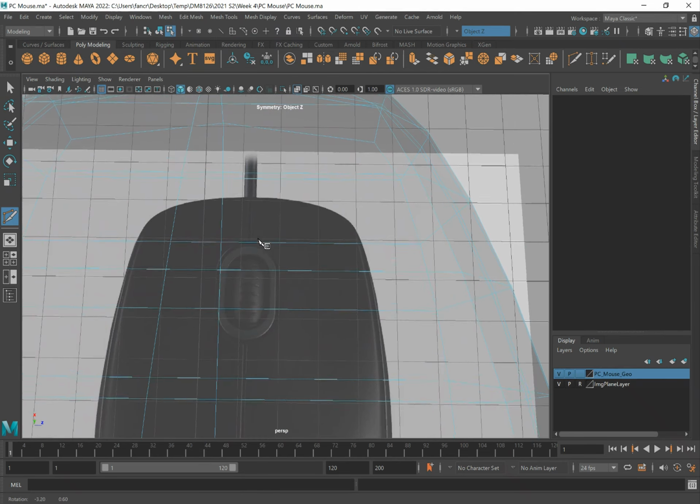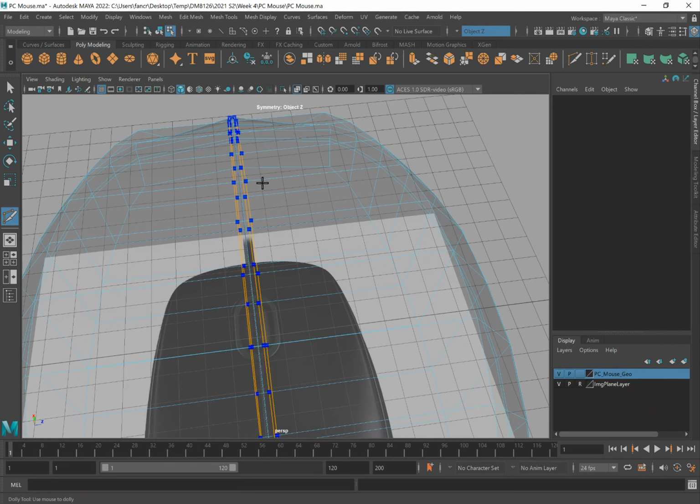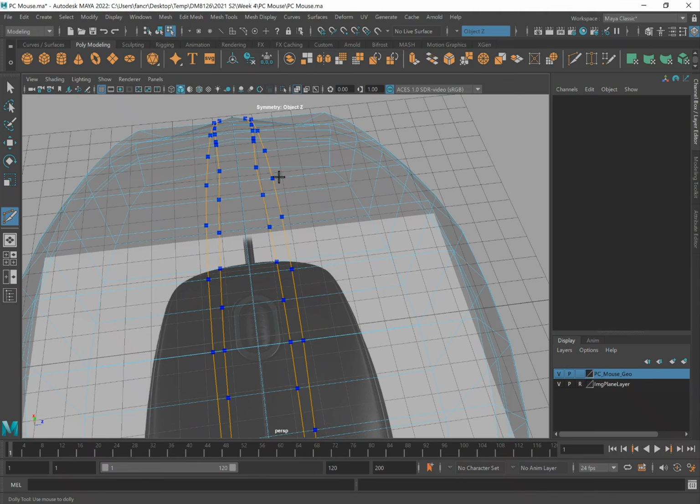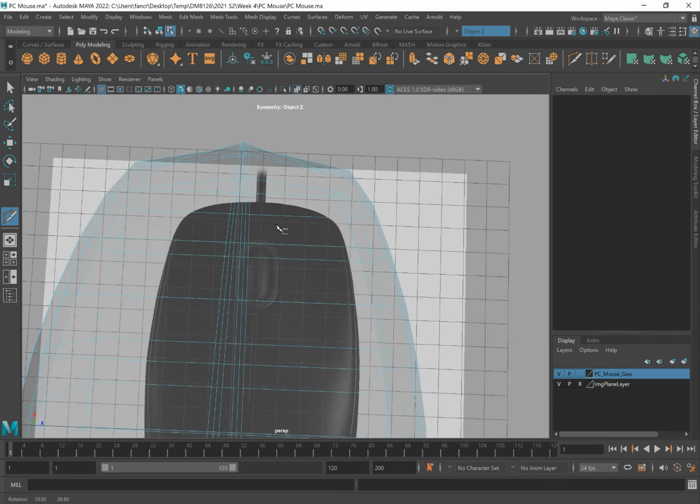So what's going to happen is I'm going to hold down my control key so that it goes into a loop. Okay, so depending on if you mouse over the horizontal division, you can tell that right now this is going to be a vertical loop, and if I mouse over a vertical division, the edge there, it's going to create a horizontal loop, right? So I'm just going to go in really close and click on it. Okay.